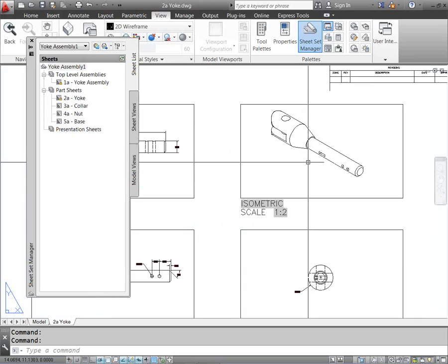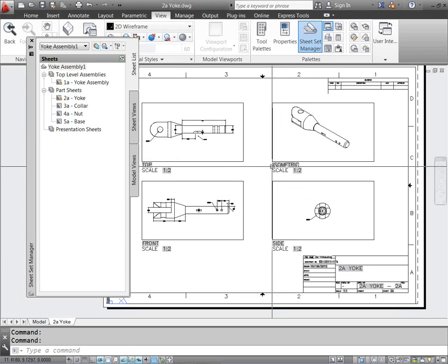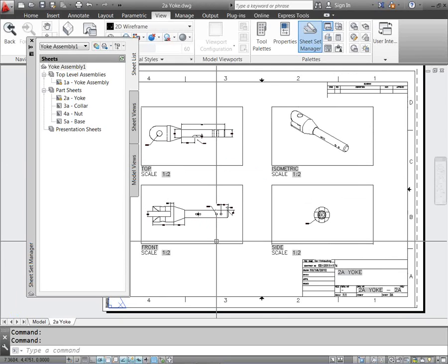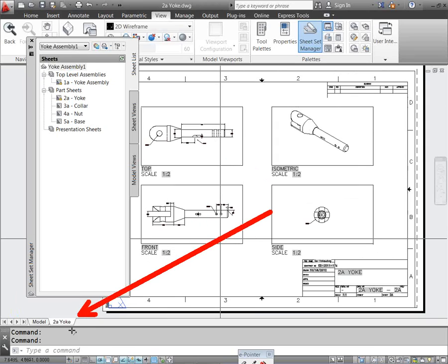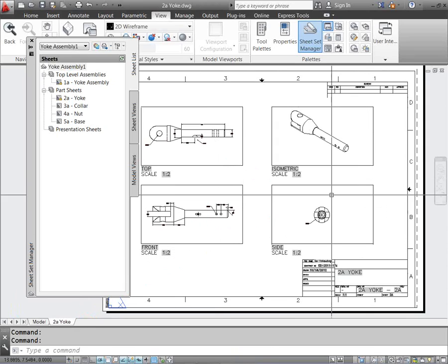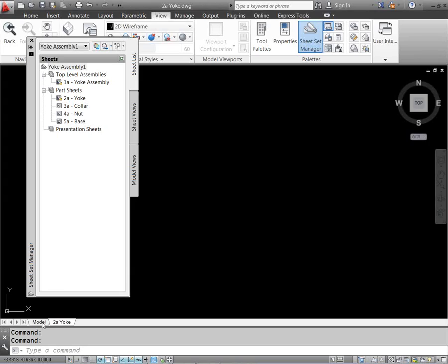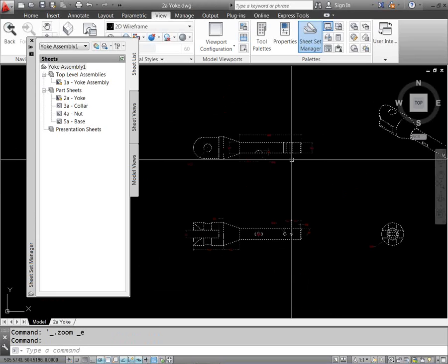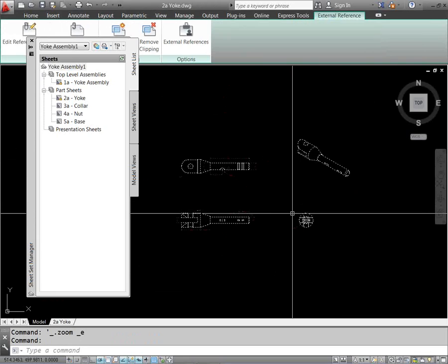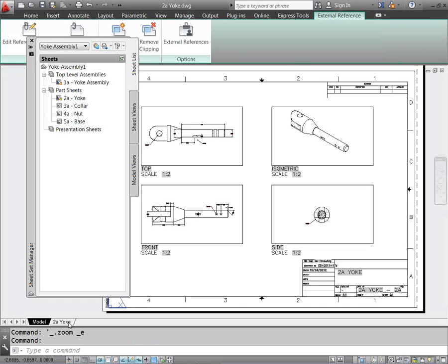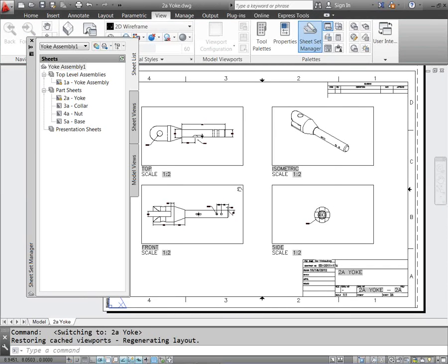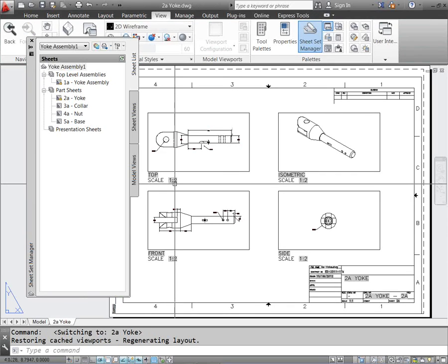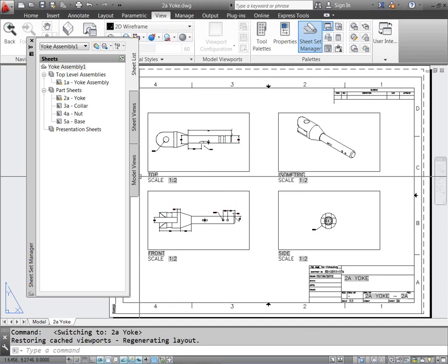So this opens up a sheet, and you'll notice that there is one tab here with 4 views on it. Just to demonstrate how this works, let me zoom extents real quick. What it does is actually XREF my working file into model space for me and generate a view, all in a pretty quick drag and drop procedure, which we'll see here in a few minutes.